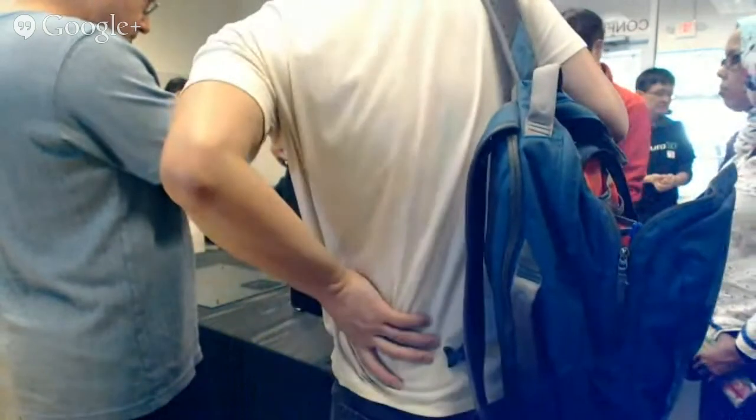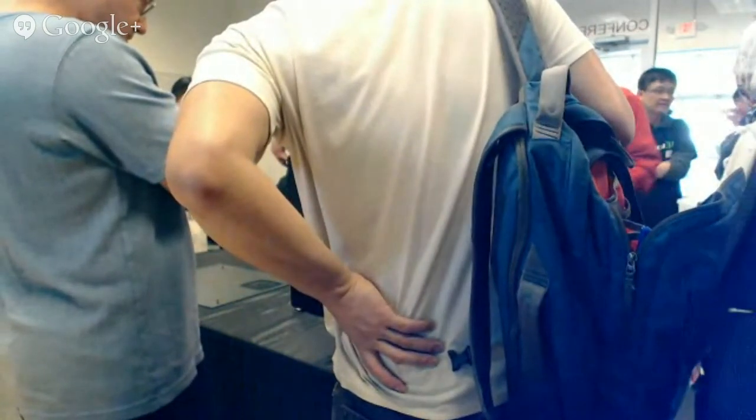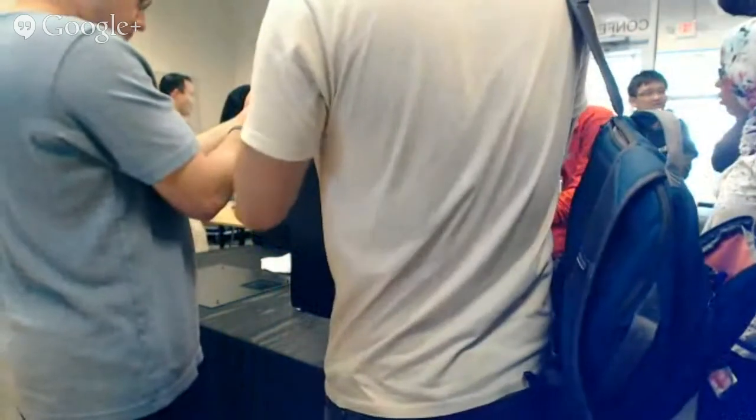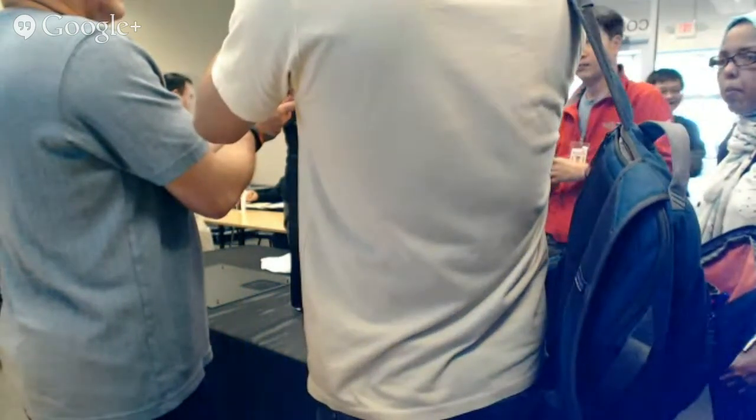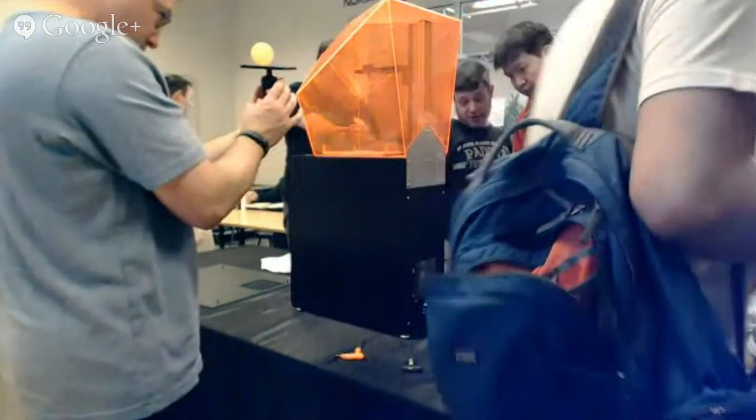An example of this is there's a flaw here. This should be perfectly flat, and it's not. This part here is warped. That's because there's an internal structure here, right? That's holding up the roof, and there must have been some detachment from the internal structure. The internal structure failed, and so then the pulling forces warped up this surface, right? So it wasn't fatal to the print, but the part is unusable because of this.